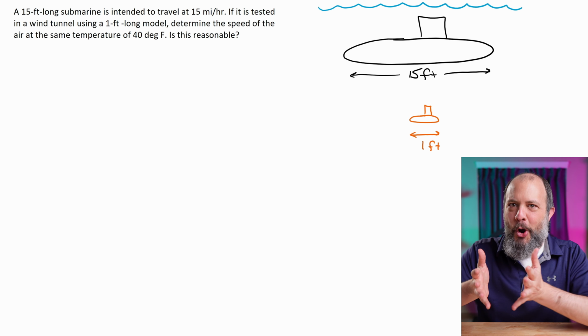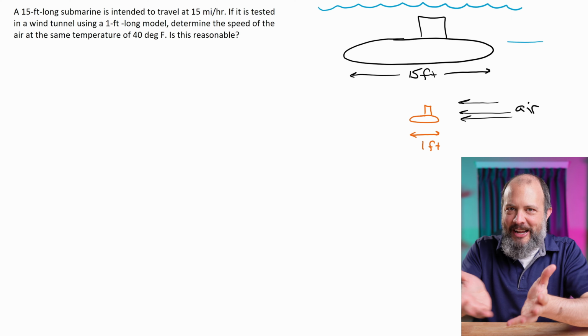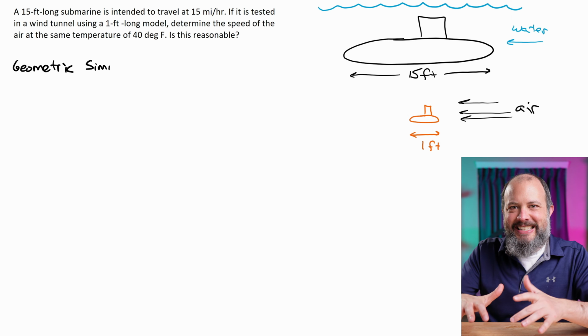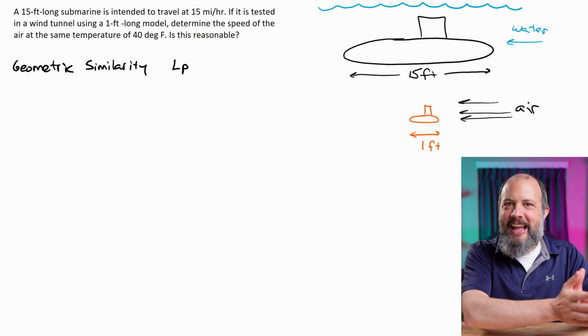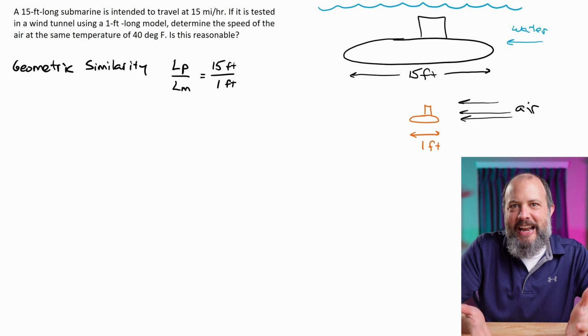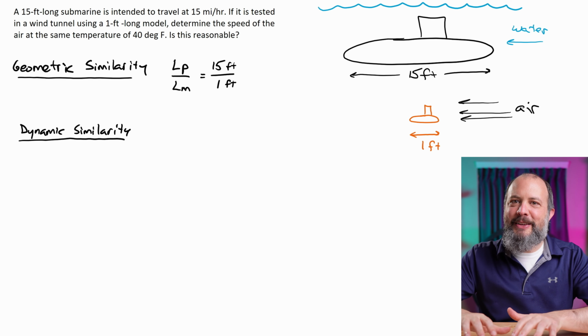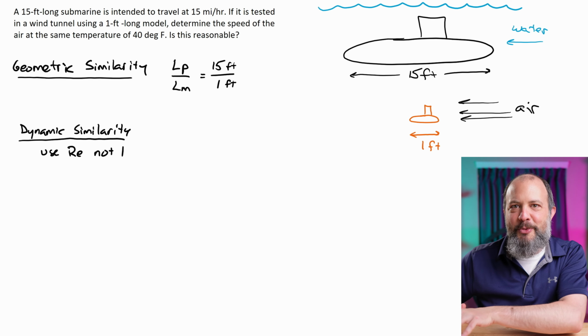A submarine would always work in water. That's right in the name, submarine, beneath water. You can actually test these in wind tunnels and actually get a representative analysis as long as the Reynolds number for your model behaves just like the Reynolds number of your submarine in water.